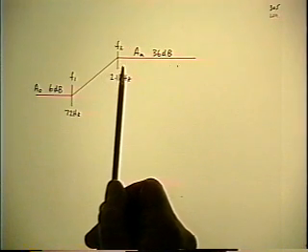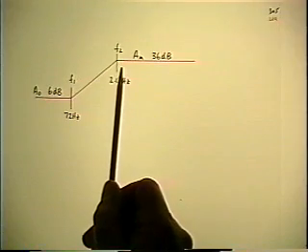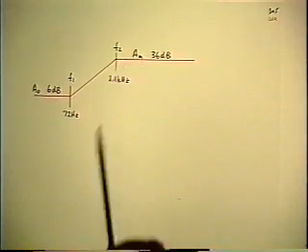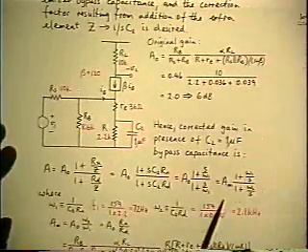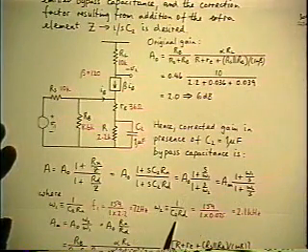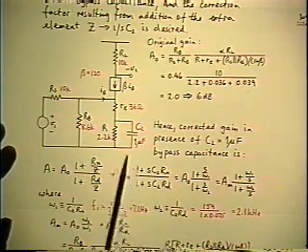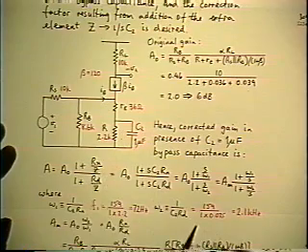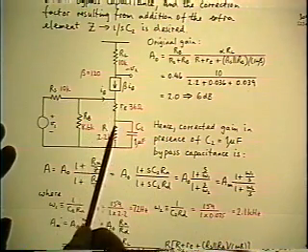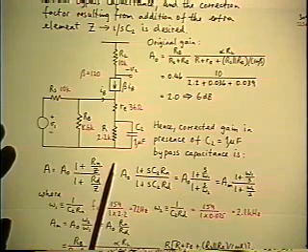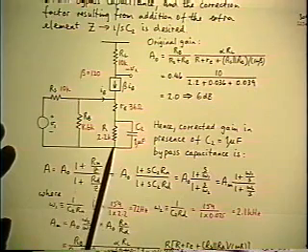So an important result from all this is it's the value of the F2 which is important for the specification, and the F2 is the pole, and the pole is determined by the RD, and the RD is the small one, 75 ohms, because it's dominated by the parallel path and not the R. The zero is determined by the R, but that's not the one that's usually important for the spec.